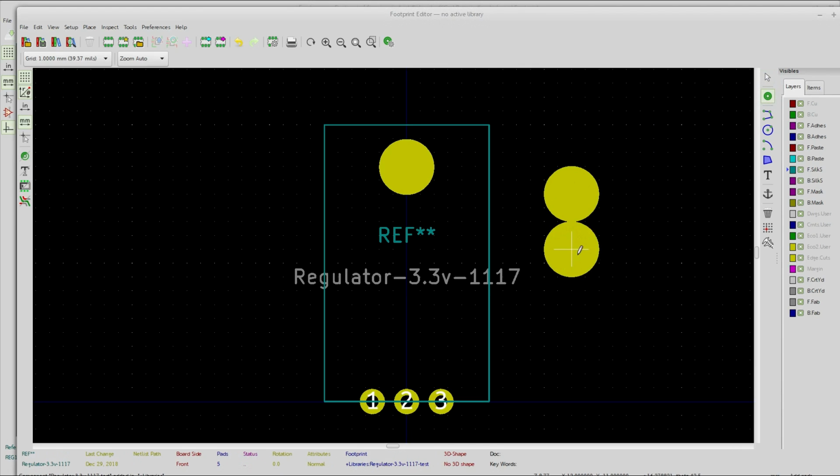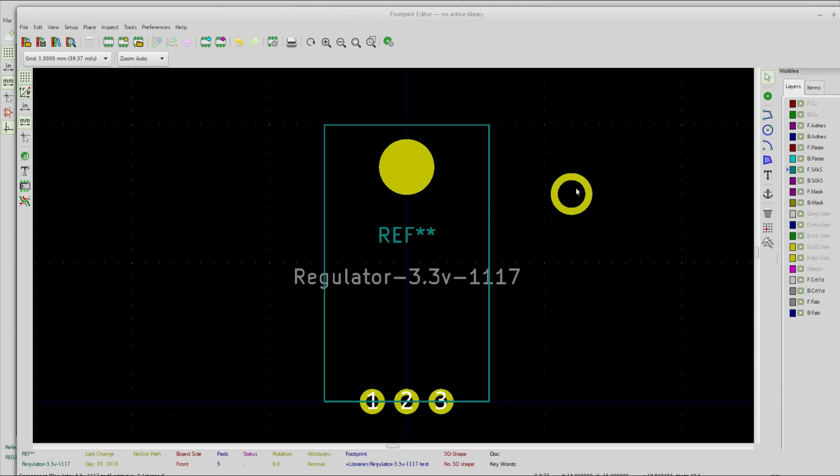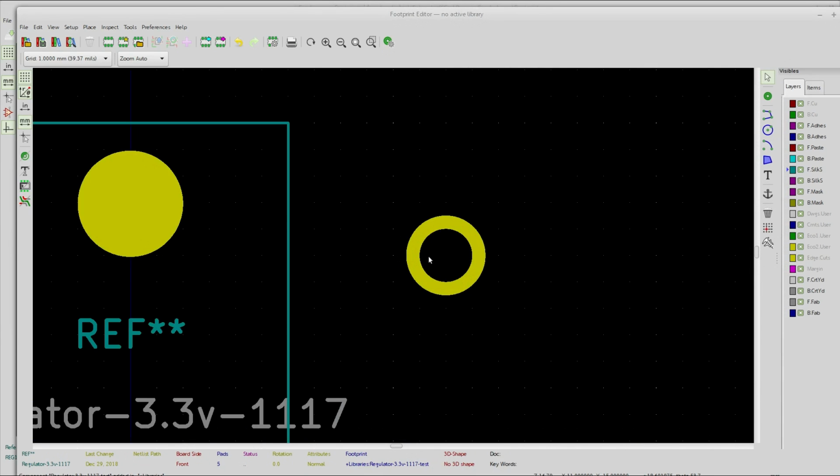So for example, if that's my pad I just made, it remembers from the last one you did. Let's say it's a through hole, and we'll say that it's a 2 millimeter hole, and it's got a 3 millimeter diameter of a pad. This dimension right in here, that's your annular ring. So now if I hit OK, you look at the diameter of this hole, and the likelihood of this being exactly in the center is probably not going to be perfect, especially if these things are really tiny, like the micro vias or just small vias that you see.